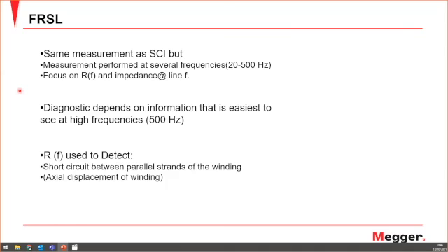So this will detect for us, in reality, the short circuit between parallel strands of the winding, what we call axial displacement of the winding. And I have maybe some slides trying to explain what we mean by a parallel strand as well.